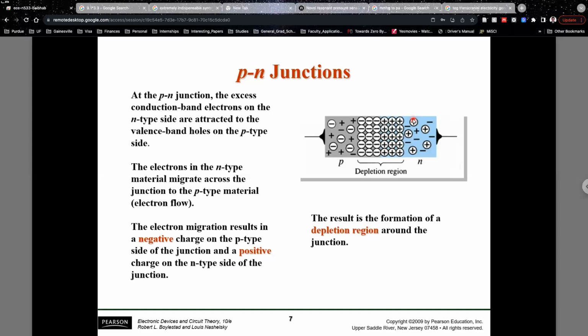Both p-type and n-type semiconductors will help in the movement of electrons. One, by creating additional electrons. So here you have additional electrons in the n-type semiconductor. On the p-type, you have these additional holes, which also help in conducting current, because an electron can come in and accept that electron. So it can also help in movement of the electron. And these are details in the device physics classes. If any of you have taken device physics, these things should become very clear.